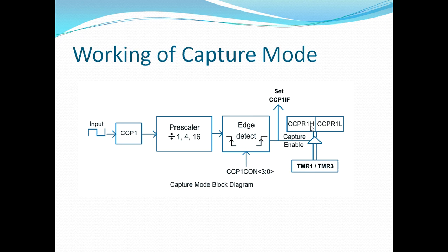So that we can measure the period between two events, one is start and the second one is stop. In between, the period used by that particular event can be captured by using this capture mode, in simple words.